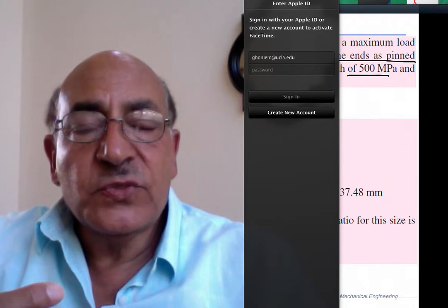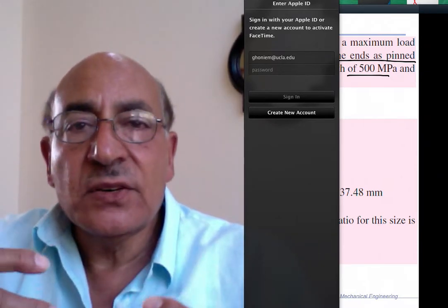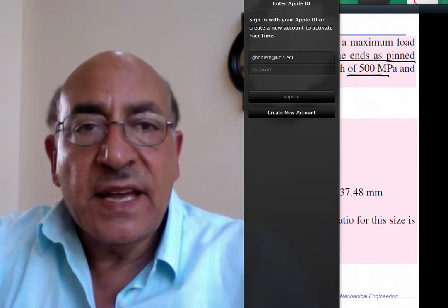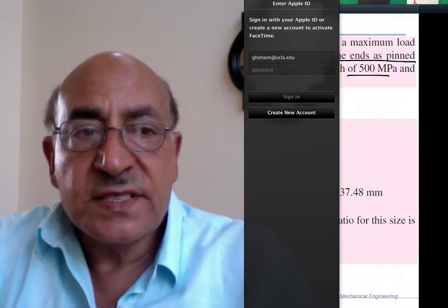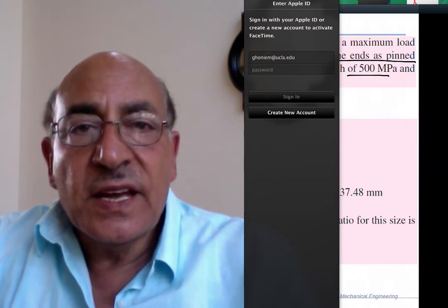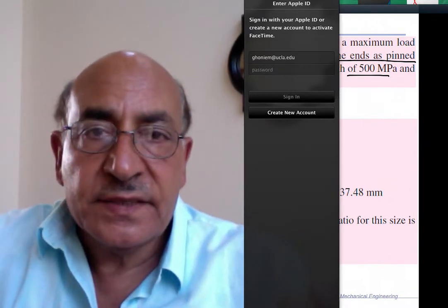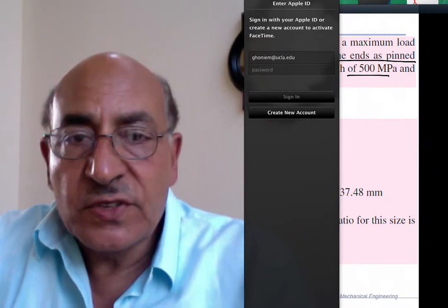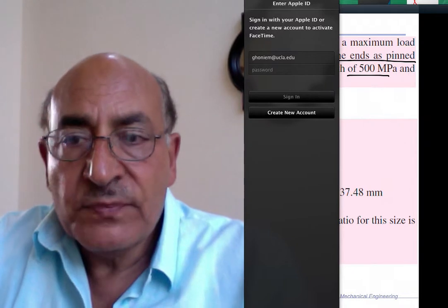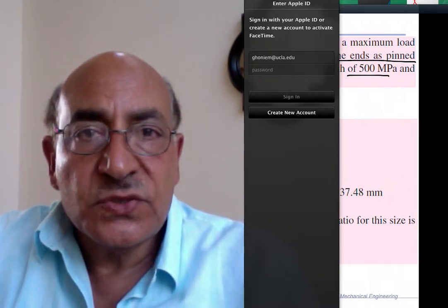If we multiply the load by the factor of safety, then we are just imagining that the load is n times what it is. So in this case, the load is 22 kilonewton, the factor of safety 4, then we would make it 88. And then start using the formulas that we have talked about before. And for pinned ends, C is equal to 1.